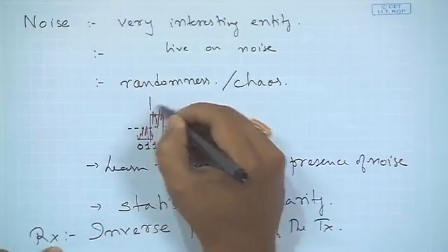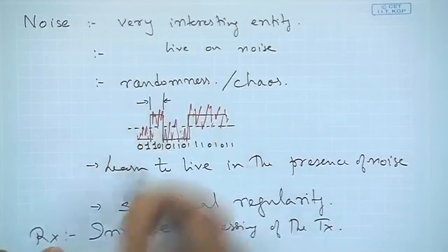And I have told you in the introductory lecture, if you have gone through it, that in a digital communication system, the receiver plays a very important role, where there has to be a synchronization entity. That means it synchronizes the carrier, which you may have studied in analog communications as well, carrier recovery, followed by timing synchronization, because as you are seeing here, time is a major factor, right?